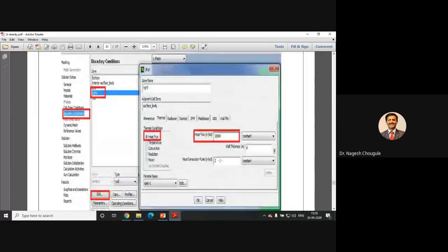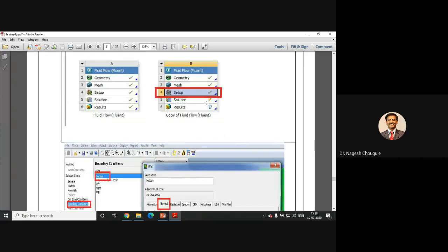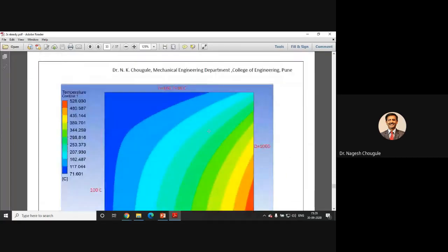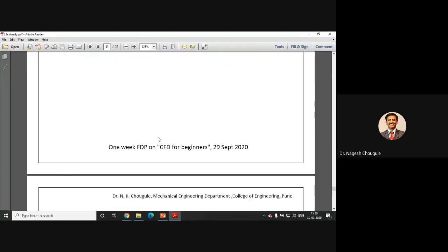So how to solve the simulation? You can right click again on the solution and click the run button. So it will solve, and once it is solved, again here you will see the green tick mark symbol that indicates that your problem has been solved. And then through the post process environment, you can see the results. You can plot the contour of temperature.